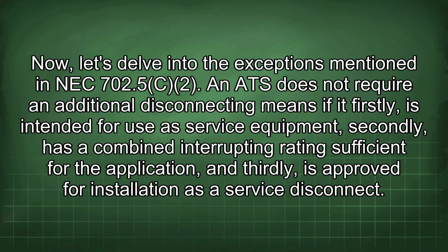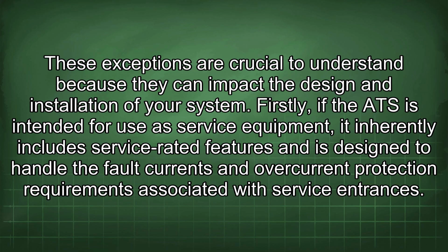Now let's delve into the exceptions mentioned in NEC 702.5(C)(2). An ATS does not require an additional disconnecting means if it, firstly, is intended for use as service equipment, secondly, has a combined interrupting rating sufficient for the application, and thirdly, is approved for installation as a service disconnect. These exceptions are crucial to understand because they can impact the design and installation of your system.